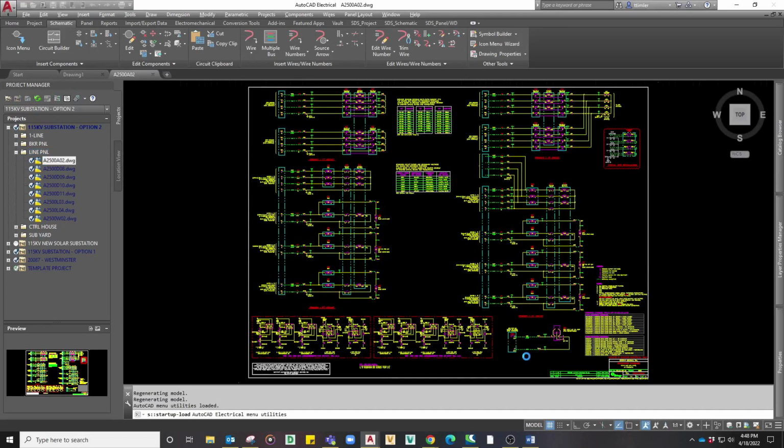Another completely different approach to converting AutoCAD to AutoCAD Electrical is to add previously non-existent schematic material into your current design standards. We've converted this drawing, as well as the standard project, to work with as much standard AutoCAD electrical functionality as possible. This option also comes with some challenges. Like before, some of the cables on this drawing are connected directly to another panel AC schematic diagram. This causes a lot more duplicate symbols to be managed through the master reference tool than previously required. The overwhelming majority of the cables on this drawing mostly reference a connection diagram or a junction box, so we've added terminals and cable marker symbols where cable bubbles previously existed.